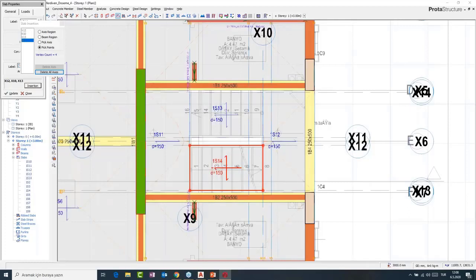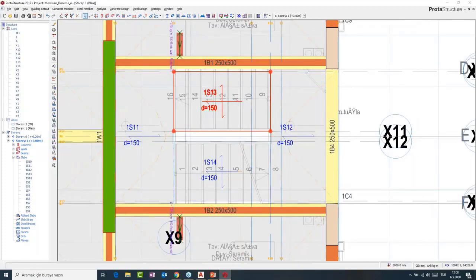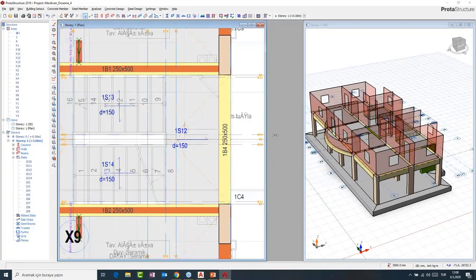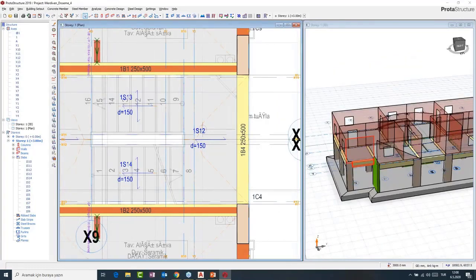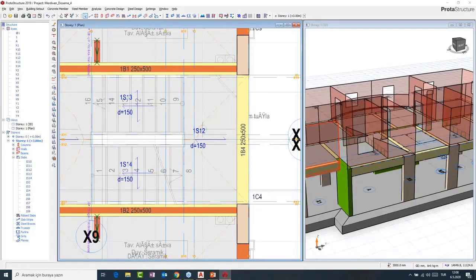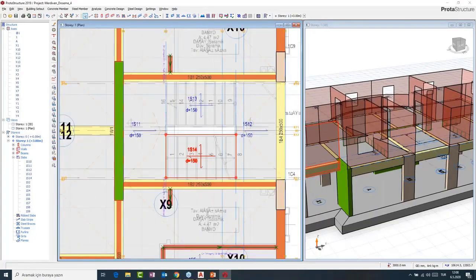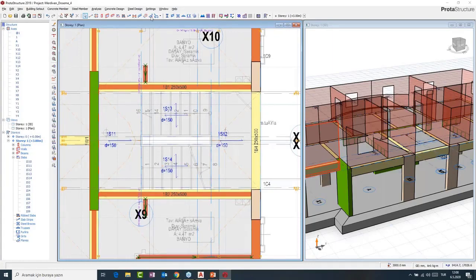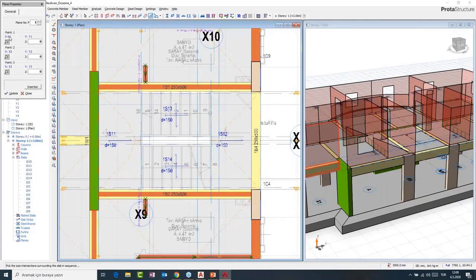You can have a look at it in 3D as well. I can just pull this along here so that you can see. This is now modeled in 2 dimensions, and I'm going to make plane definitions now. In order to do that, I can go to the plane definition options right above here. And you'll see in the properties 3 points here, which are referenced in the slabs.